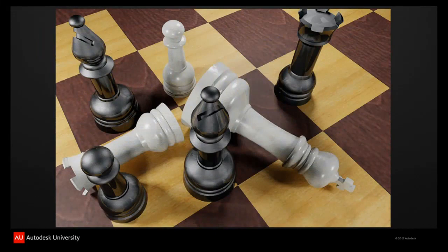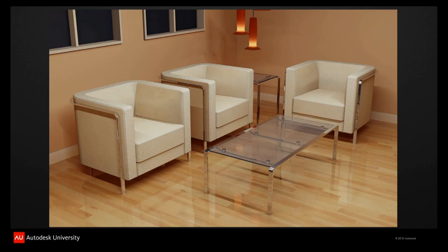Here's another larger example. A few more pieces there, but just to give you an idea. And you can see the soft cast shadows. Here's the previous drawing that we saw before, completely illuminated with point lights. I've even put some point lights in the small hanging glass fixtures there. Those are just revolved shapes that are hollow, and then I applied a glass material. Put the light source up in there and the light's coming through.